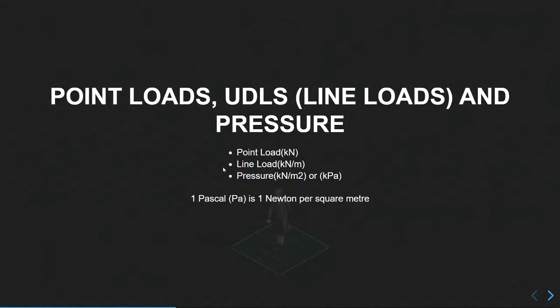So if I take this pasta and think about the load that's getting applied to it, that finger load that I've just applied, rather than trying to compute all the little atoms and their electromagnetic relationships with the pasta to work out all the different loads, we can abstract this all down into point loads, UDLs, that's uniformly distributed line loads, or line loads, and pressures.